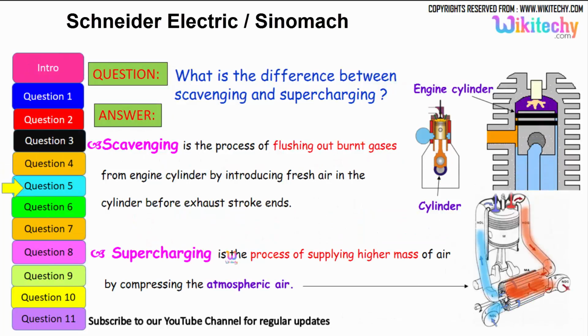Let's move on to a different question. What is the difference between scavenging and supercharging? Scavenging is the process of flushing out the burnt gases from the engine cylinder by introducing fresh air into the cylinder before the exhaust stroke ends.